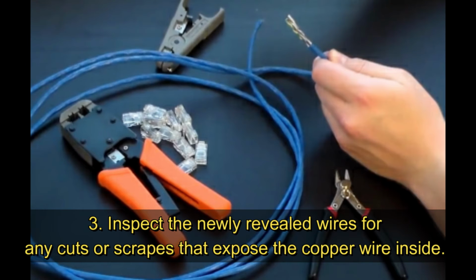Step number 3. Inspect the newly revealed wires for any cuts or scrapes that expose the copper wire inside. If you have breached the protective sheet of any wire, you will need to cut the entire segment of wires off and start over at step 1. Exposed copper wire will lead to crosstalk, poor performance, or no connectivity at all. It is important that the jacket for all network cables remains intact.